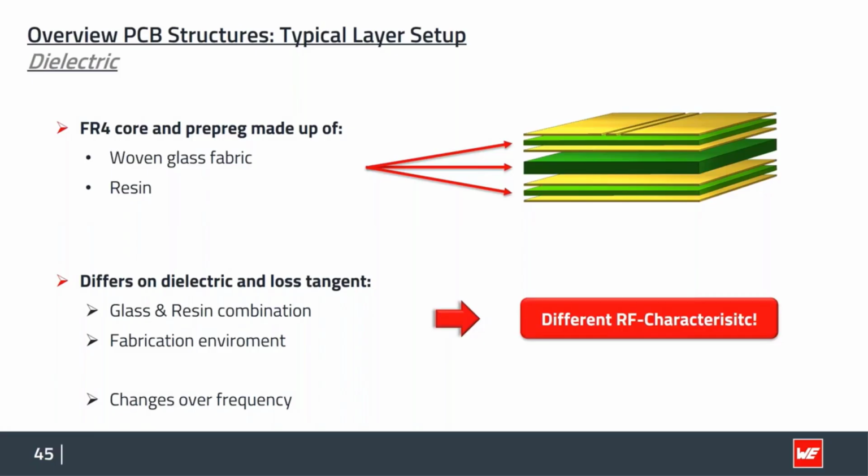And this means that your copper layers do not all go 100% to the edge of the PCB, but there is 1 or 2/10 of FR4 material in between, which needs to be known, because otherwise you will create a great slot antenna. Of course, there are different options like metallized edges of the PCB that cost money. For many cases, you don't need that, but you can also close your gap antenna in a different way, which we'll see in the simulations afterwards.